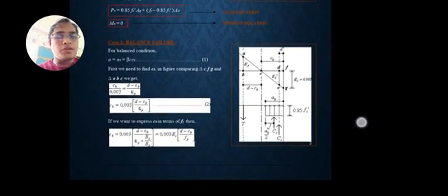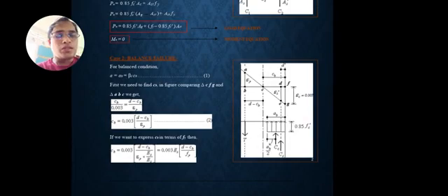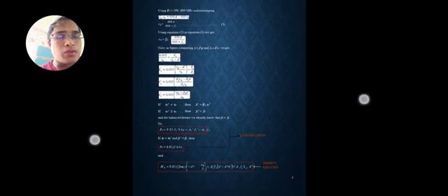For balanced failure, first we need to find a from the figure. So, if we want to express in terms of d, using E_s equal to 200,000 MPa and rearranging, c_b is equal to 600d over (600 plus f_y). So that is for balanced failure, the formulas first.